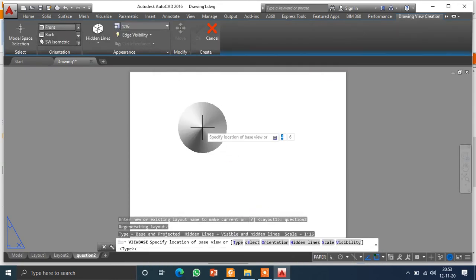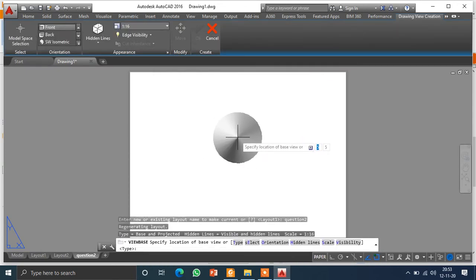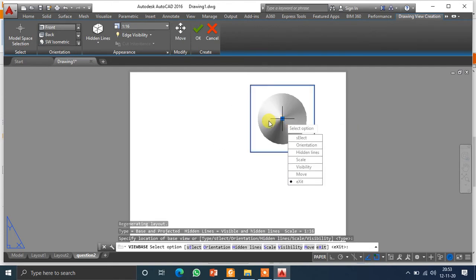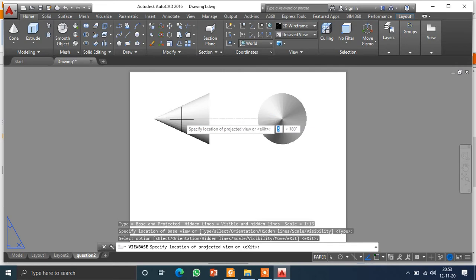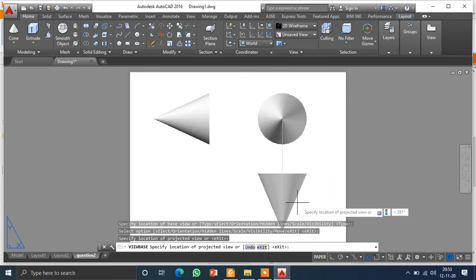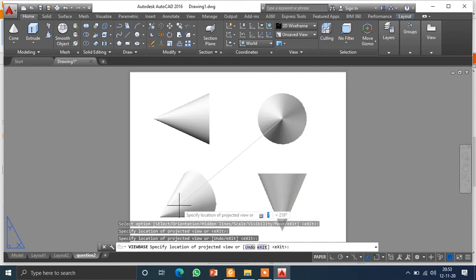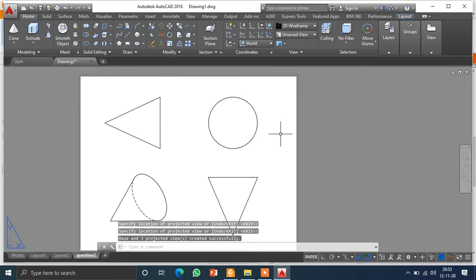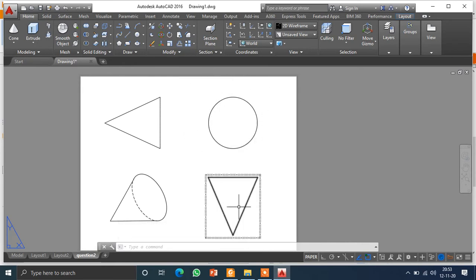Okay, so this is your front view. Make sure the front view is kept here rather than keeping it on the other side. This is your right side view. When it is kept on the left side, that becomes the right side view, and this is your top view. If you want, you can plot the isometric view also. So which views are giving the exact dimensions? The base dimension is being given in the front view, and in the top view you can visualize the total apex height or the altitude height.